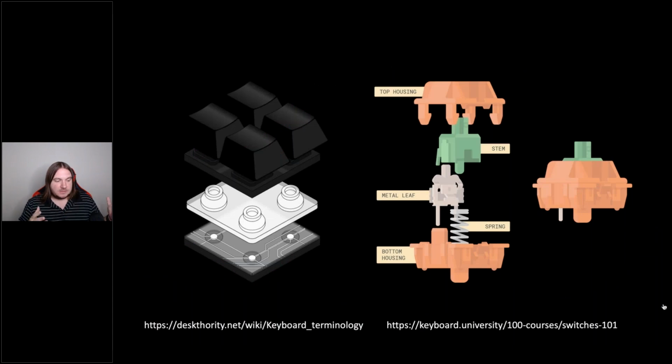So a mechanical keyboard is similar to a standard keyboard, or a membrane keyboard, as it might be known. So on the left here, those black 4 keys and that little diagram there, I'll walk through that real quick. So it's like a standard membrane keyboard. You have your key caps, which are the actual things that you press, and then they plunge down into a layer. It's like silicone, and it presses down a plunger, and then under that plunger, you can see those little traces on there with the circles. That actually has 2 pieces of metal that when pressed down will connect and complete a circuit. And that's a signal to the PCB running the device to send a key code across USB. And that's fine, that's cool.